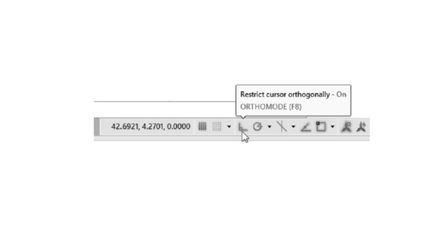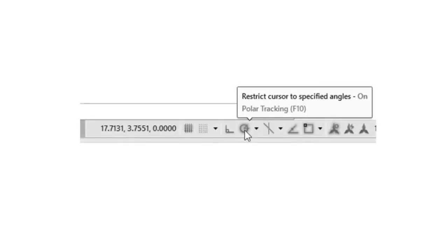Fourth, continue with the Line command. Move the cursor to a point below and to the right of the first point you selected and click again. You've just drawn a line segment, and a second rubber banded line appears. Fifth, if the line you drew isn't the exact length you want, you can back up during the Line command and change it.